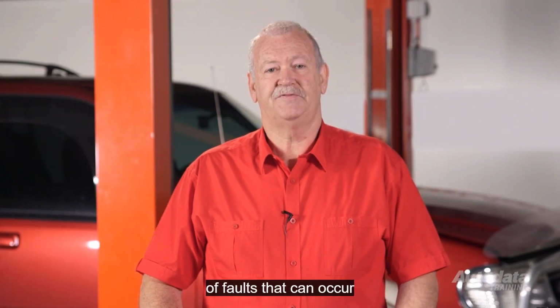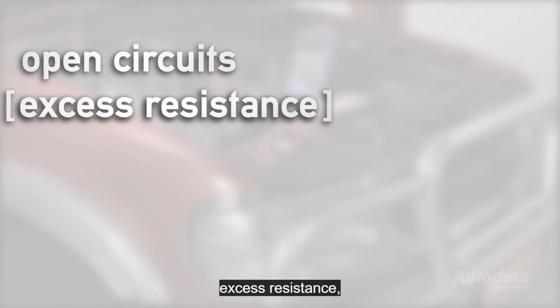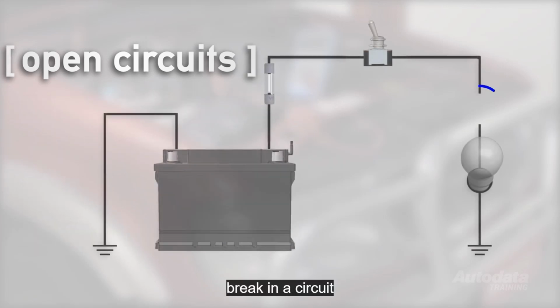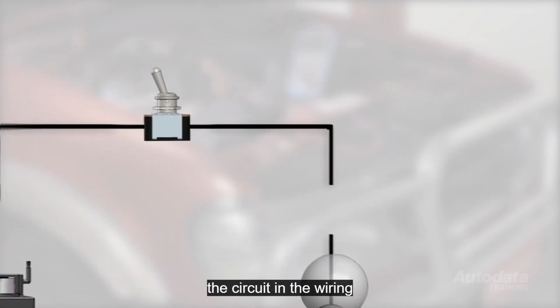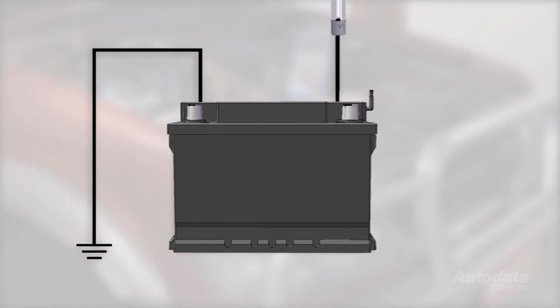There are many different types of faults that can occur in electrical circuits. We'll be looking at open circuits, excess resistance, short circuits, short to ground, and shorts to voltage. An open circuit is a break in a circuit that stops current flow. This can occur anywhere in the circuit, in the wiring, in the component, in a fuse, or in a ground.